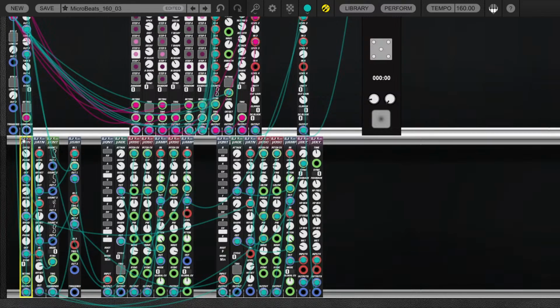What makes this melody special is that this sine LFO has the combine output, which is a combination of all 3 sine LFOs, and since they all move at different speeds, we get a pretty complex pattern, or a pretty complex control voltage for the sample and hold to sample and quantize into pitches for the oscillators.